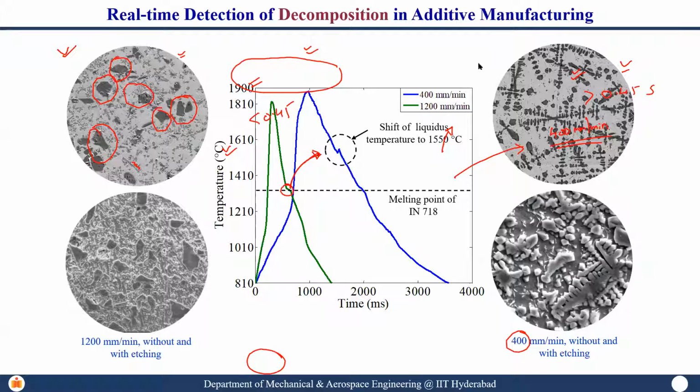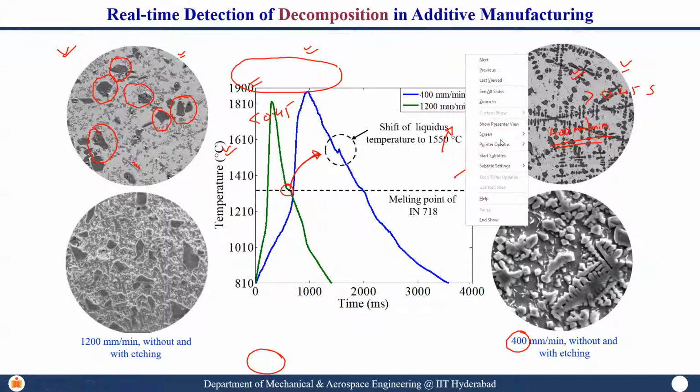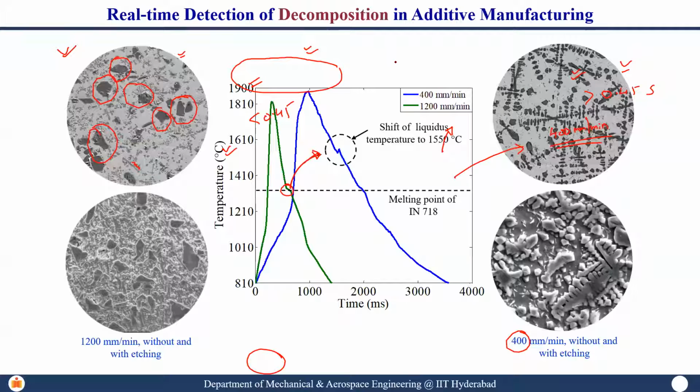And this is also what we have done here. If you see, this is molten pool lifetime. Once again, you cannot measure the molten pool lifetime directly. So what we did is we kept molten pool lifetime as a function of cooling rate. We generated an equation for the correlation between these two, because if the molten pool lifetime is high, the cooling rate will be less, so they are inversely proportional. You can determine those types of equations and then determine the cooling rate, so you are estimating the molten pool lifetime, and then you control the process.